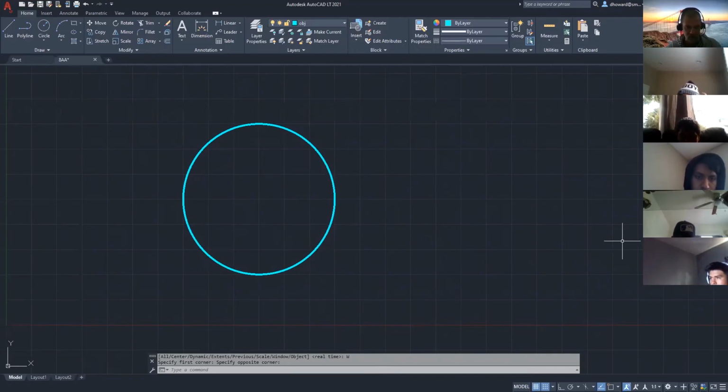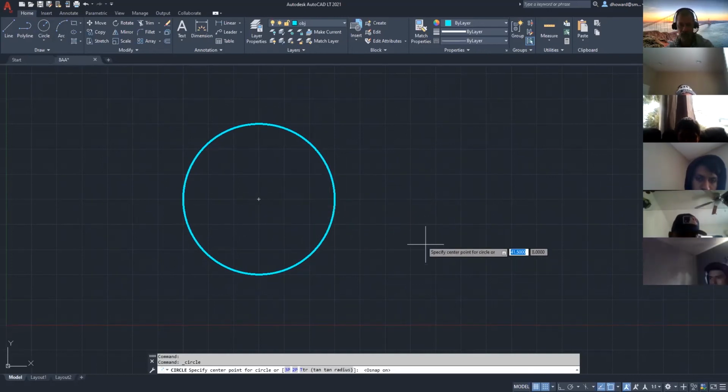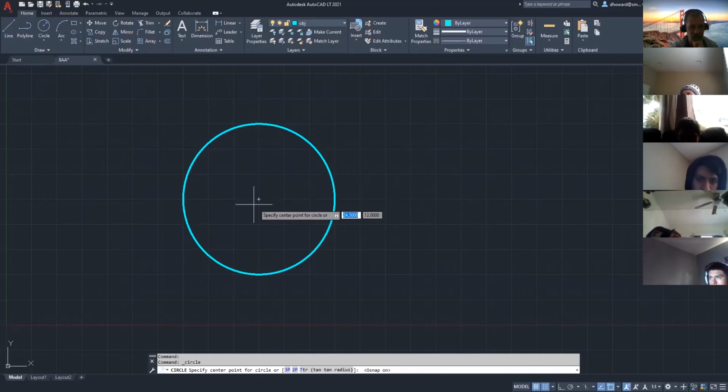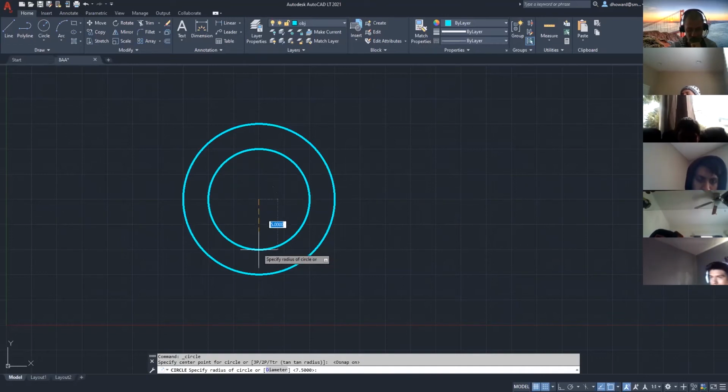All right. And now I'm going to make the hole that's inside of it. And I want to be sure those are on the same center point. So at this point, you might decide to turn on the object snap. You can see that the center is now lighting up. As you drag your cursor across the previous circle, you can see the center lights up, and you can click on that, and that way they will for sure be concentric. There you go.